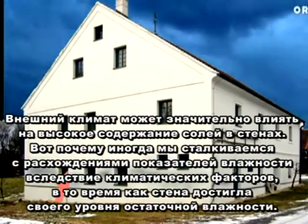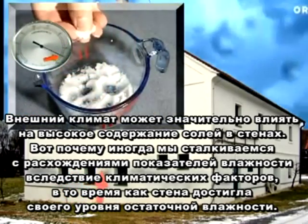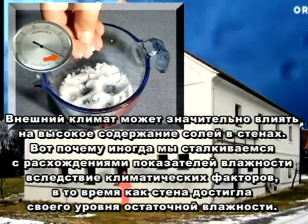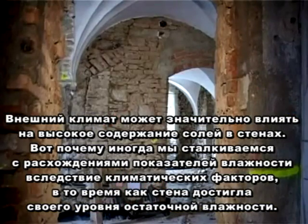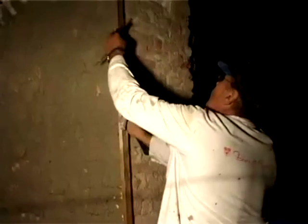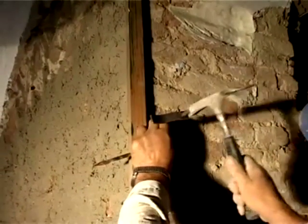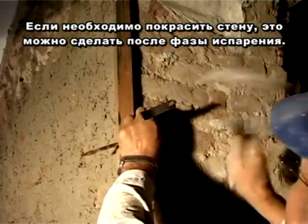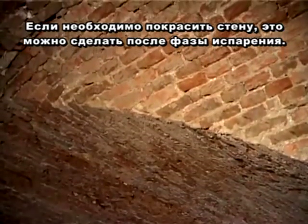The external climates might play a major role when walls contain a lot of salt. This is why we occasionally encounter moisture variations due to climatic factors, although the wall will have achieved its level of residual moisture. If the wall merely needs a new coat of paint, it should be painted after the evaporation phase.